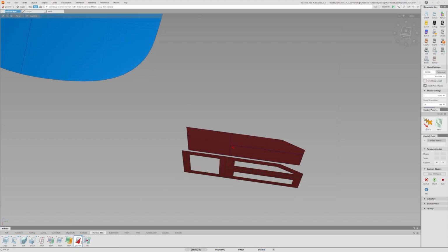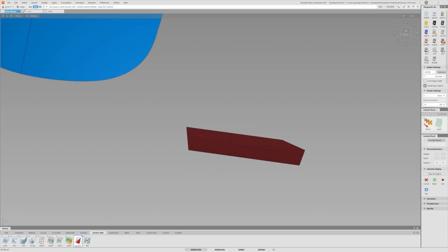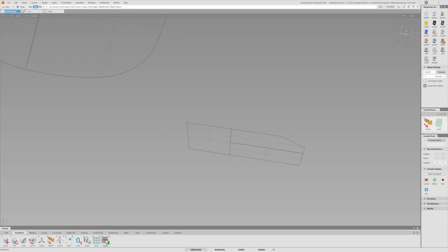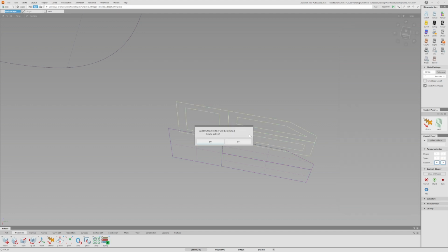Those 3 are red, which means it's going to offset towards me where I want to offset the other way. So you need to make sure that you flip those surfaces if you want to offset in that direction. Now if I try it again with the player and keep the same numbers, it offsets in the right direction, but it's giving me 3 surfaces offset the same way, and the tubular offset is applied within each surface but not to the whole body, which is what I want. So what can we do?